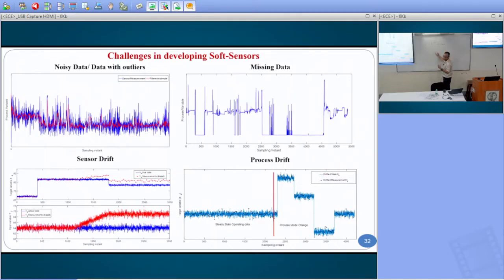So I add the error to the prediction, and immediately there will be a shift in my predictions. Then again it can come closer. After a certain time again there will be a deviation. Whenever the new sample comes, I again add the error to it, and it pushes back again. I keep updating this error as and when my measurement comes from the plant.